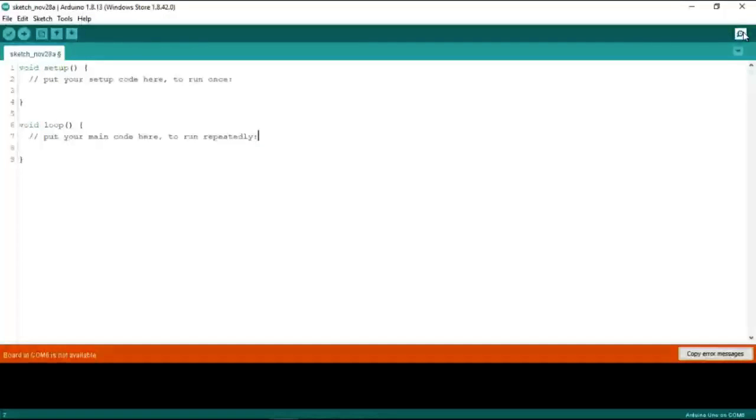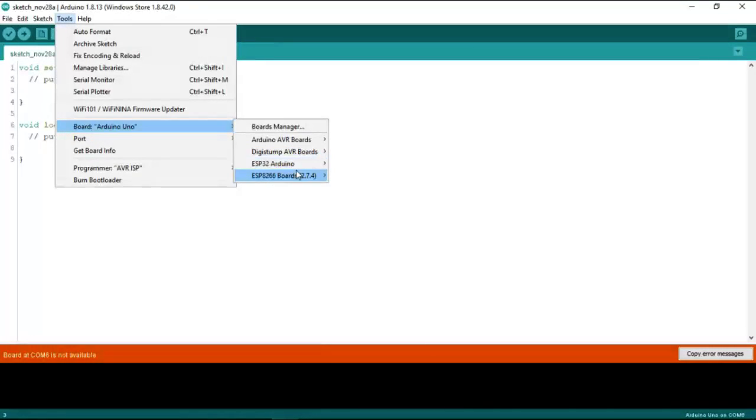I've installed a lot of libraries for other brands of boards like the ESP32 and others. So for you, your mouse is here, and you simply open this long list of Arduino boards, not this small one. You choose the correct Arduino. For example, for Maker Nano, you use Arduino Nano, and then you see at the bottom right here, Arduino Uno on COM. This is mine. It should change to Arduino Nano. See, it changed to Arduino Nano.